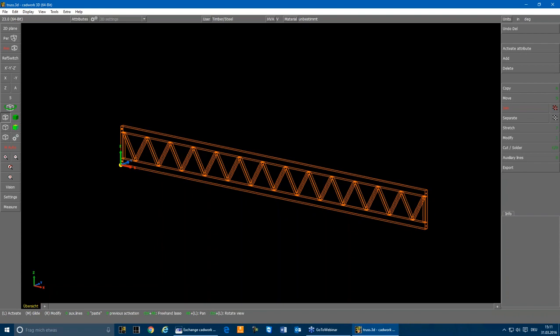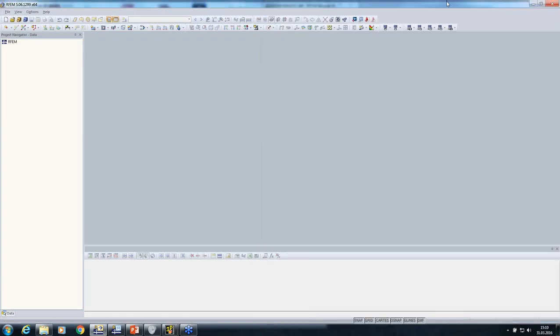Okay, thanks, Christian. I will actually split this presentation into two parts. What I'm going to do now is import this truss beam via DXF and via .stp format, and the design with this truss I will do with Eurocode 5 with the British Standard annex from the United Kingdom. In the second part we're going to do a CLT position, which is a little bit more complex, and I will do the design with our pretty new American design modules for some parts.